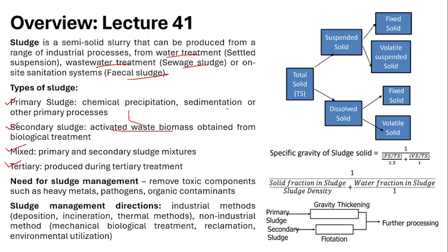We have a secondary clarifying tank, right? So after the activated sludge process, this tank will separate the clear water from the sludge deposited at the bottom, right? So this is where the secondary sludge is produced. So the next treatment step is the tertiary treatment. Tertiary sludge is also produced from the tertiary treatment, like after the disinfection and oxidation process, breaking down of the organic matter, some amount of sludge will be produced.